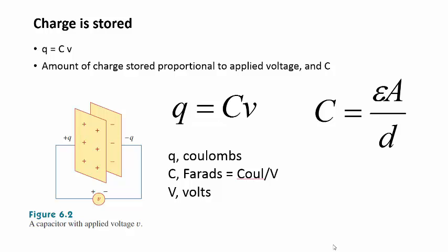So capacitors store charge. This is the defining relationship for a capacitor: charge equals capacitance times voltage. So the amount of charge this device will store is proportional to the applied voltage and the capacitance, and capacitance is tied to the physical construction of the part.